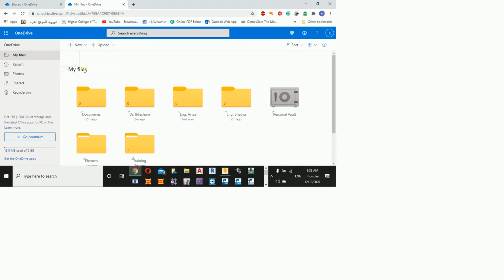Okay, and I'm assuming that he is doing a center to center, and in both scenarios, I'm going to explain for you. Whatever we were saying, Dr. Ihtisha, that normally in CAD and Revit, we are doing positioning of the columns. Columns are rectangular. Now, in most of the cases, if you transfer them to structural software, it will be only linked as center to center.